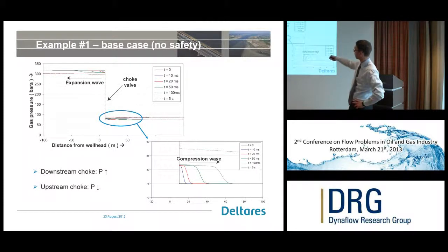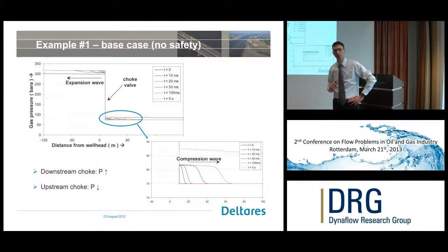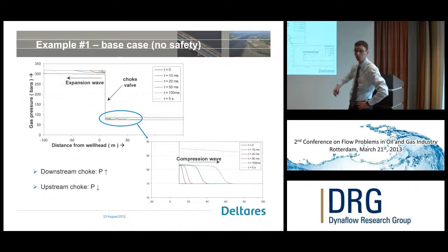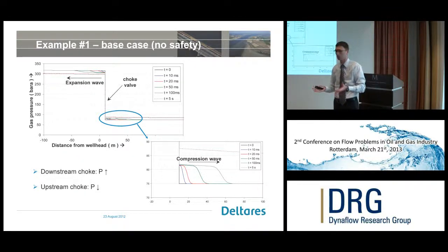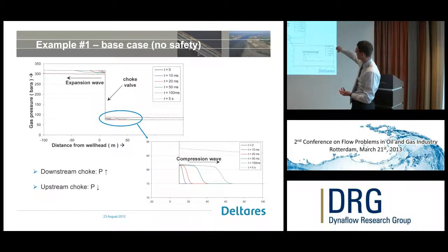Well, the best way is then to keep the pressure upstream of your choke constant at the closed-in tubing head pressure. But if you see that the pressure already decreases quite strongly, and that depends of course on the CV of your choke valve after breakout, but if this pressure goes down, then that means that the pressure wave that goes into your low pressure system is also smaller. So that means, when you do these dynamic simulations, you can also avoid being too conservative as well.